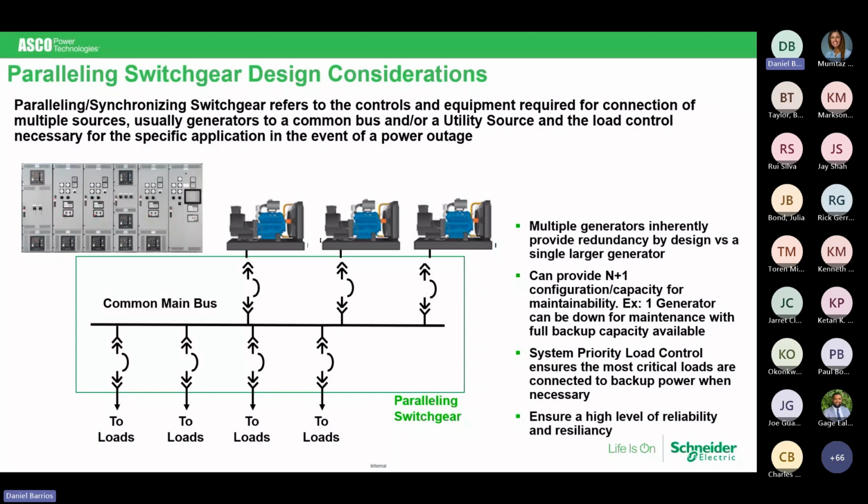We are taking responsibility. We are taking the outage of the utility. We will initiate as we go through this presentation. We will tell all 3 generators to start in order to make sure at least the first one gets online and able to meet your life safety loads in 10 seconds. We'll delve into that a little bit more deeply.